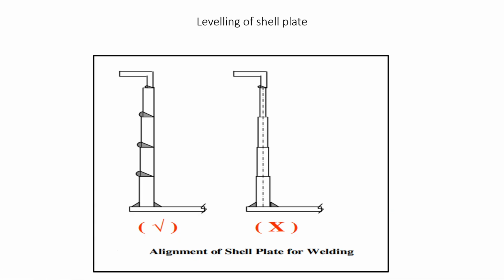And when you are doing the fabrication, you see this is the shell, this one is the vertical shell. You see the inward curve, or girder, inside it should be perfectly matched. The bottom shell thickness will be more, because the force at the bottom will be more. So to save material, we are gradually reducing the shell thickness.